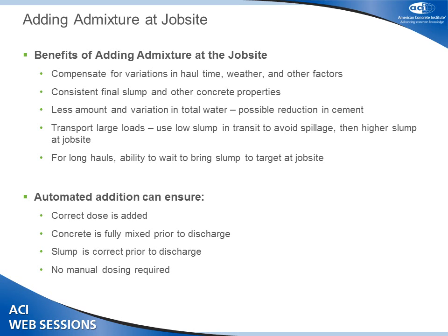And by doing it in an automated fashion rather than a manual fashion, where the driver has to get out and manually pour in admixture, or you have to have manual tanks and dispensers on the job site, automated addition can ensure that the correct dose is added, that the concrete gets fully mixed prior to discharge, and that the slump is correct. And then obviously you don't have to deal with manual additions.